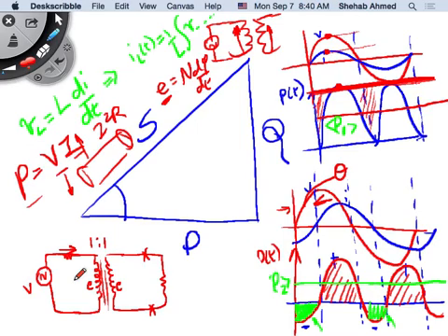This current is a small amount. Dr. Haytham probably called it excitation current in a transformer, right? Or the magnetizing current. Remember that you were drawing the magnetizing current? So this is the excitation current of a transformer. Is this excitation current used to transfer power from my source to my load? It's not, because there's no load here, it's an open circuit. But is this excitation current necessary or not? Yes, it's necessary because it's doing this E thing. It's creating this back EMF voltage through the creation of flux, right?